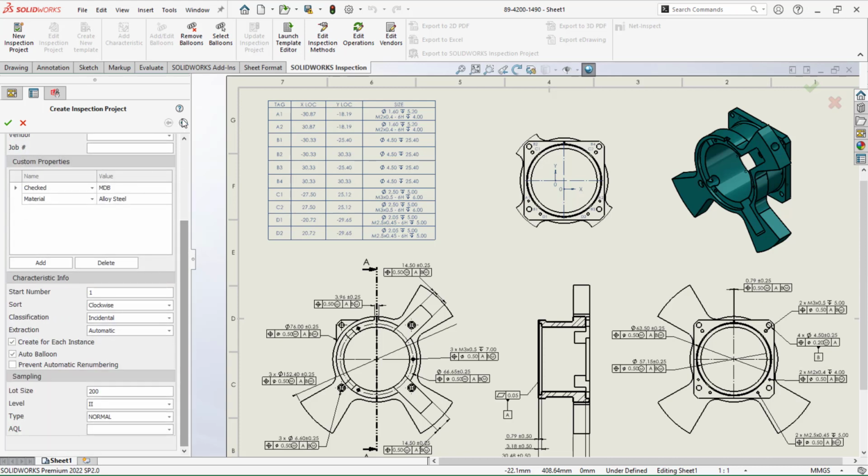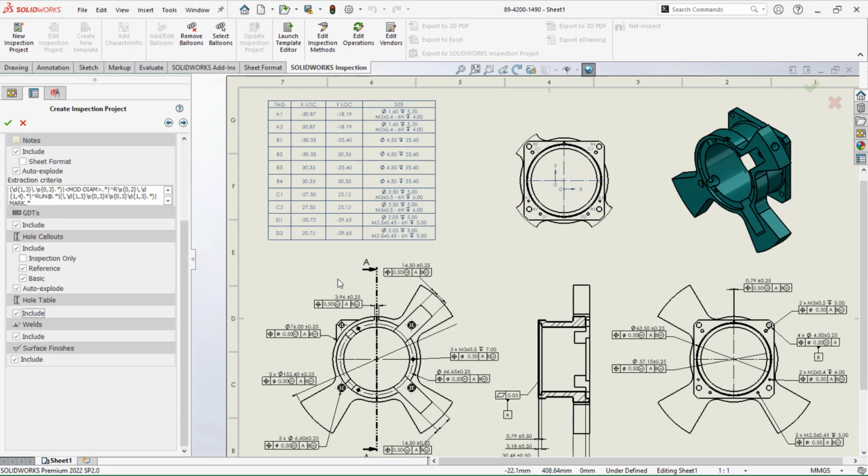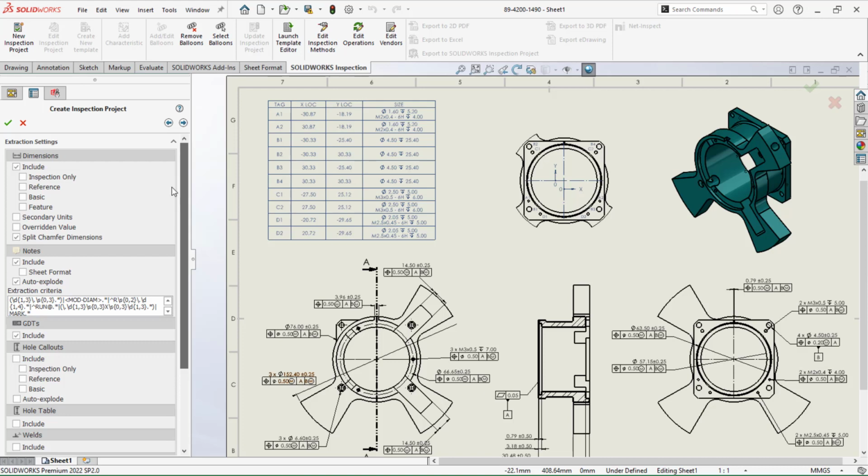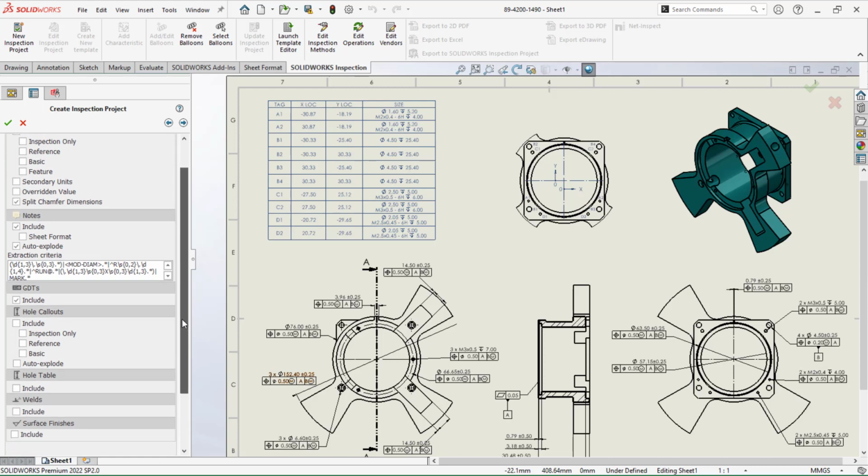By default it will be saved, and all the things we had specified during that particular inspection report will be added here by default. If you want, you can remove, or if you want, you can simply add everything here. Right now I'm going to look only towards the GD&T things, so I'll only select this, and once you're done with this, you can simply include one more thing, that is the whole table, which is the advanced capability of SolidWorks Inspection, we can say.